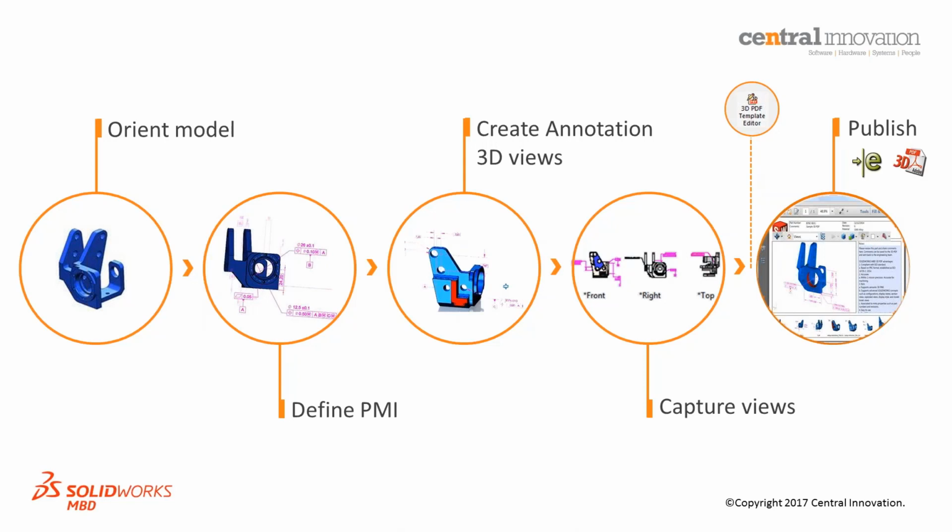So if you break down MBD into 5 quick steps, it could be just starting off with 1, activate your MBD in the SOLIDWORKS tab. Then secondly, you just start defining your product manufacturing information. So you've got options of both freestyle and intelligent dimensioning, tolerancing, and annotations. So you can utilize the DimXpert, which is quite a popular tool among all the SOLIDWORKS users, to add all the dimensioning that you require. You can also use the existing feature dimensions, which are put in by the modeler or the designer and which are already existing in the model. You can set up your geometric tolerances, styles, datums, tree views, and I'll dive deeper into that, so you don't have to be intimidated with all what I'm saying right now. But that will be your second step.